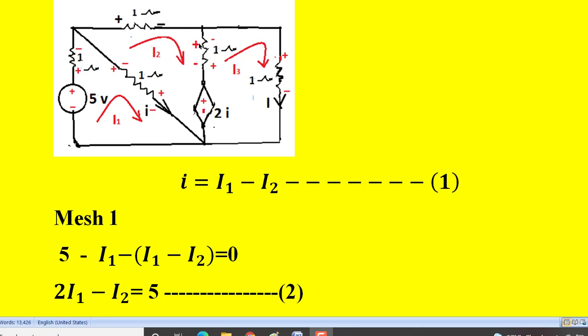Next, again here we have the plus here, minus here. So going from positive to negative, we call that a voltage drop. Voltage drop will get the negative sign. So minus 1 into I2, there is another current called I3 flowing. So I2 minus I3 into 1. So that is the second element. Next, there is another voltage source here.